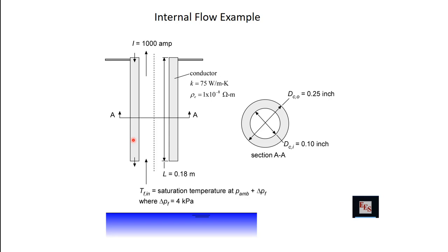So there's different ways of cooling these magnet leads. One is just conductively cooling them. So you cool the cold end, and you hope that the rest of it doesn't get too hot. We talked about that, I think, before in a different example problem. More common is actually what is called vapor cooling. So you vapor cool the current lead.